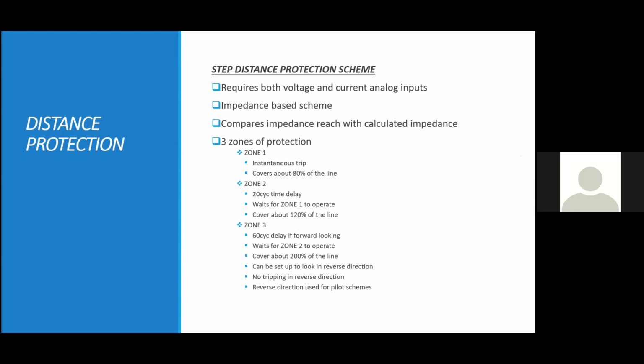So now we'll be talking about step distance protection scheme. For implementing a step distance protection scheme, you require both voltage and current inputs to a relay. As this is an impedance based scheme, the relay will calculate the impedance of the fault to see if the fault lies on the line or not.